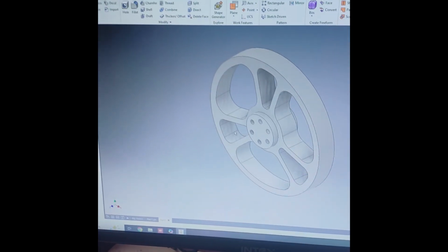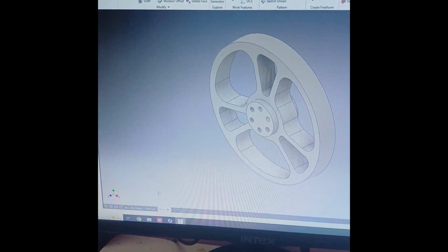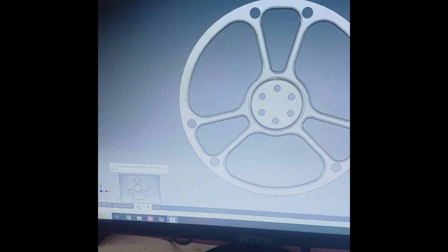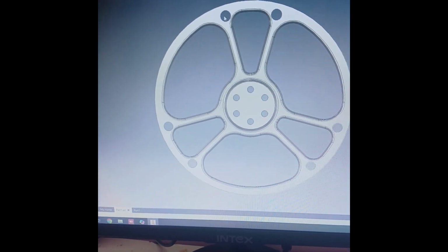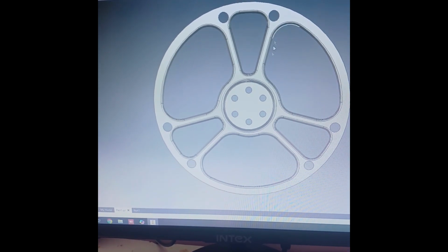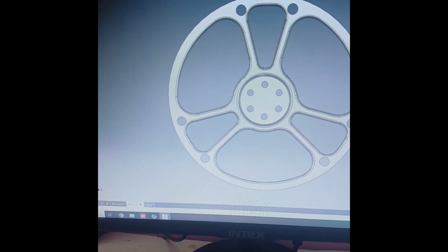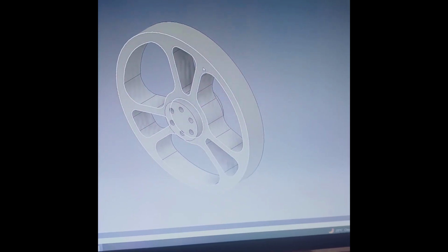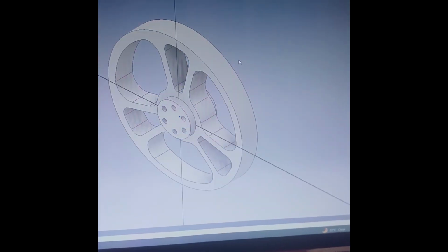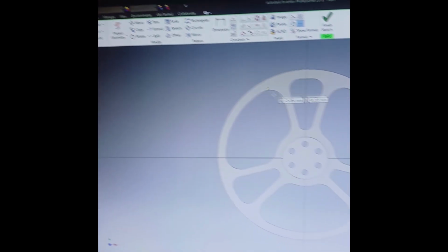Okay. Now here go to this previously made part. So this profile we have made, these profiles we have made. Now we will make this circles and the fillet. Go to the making profile. Now select this face, go to create sketch, and here go to the circle command.